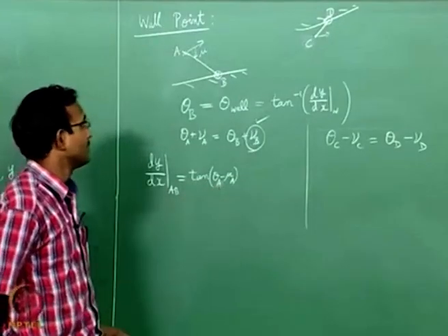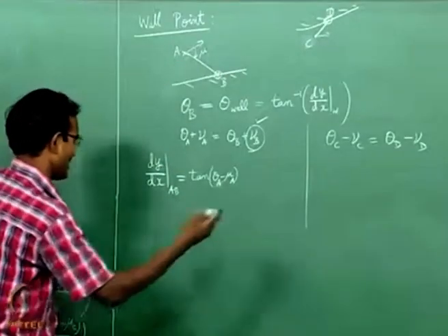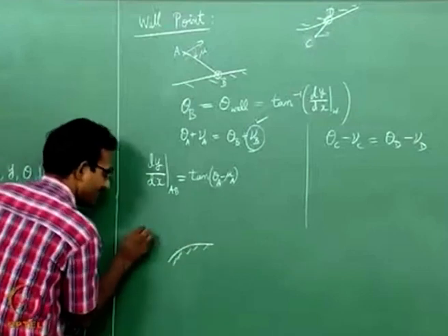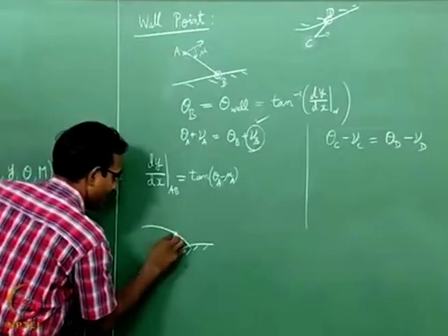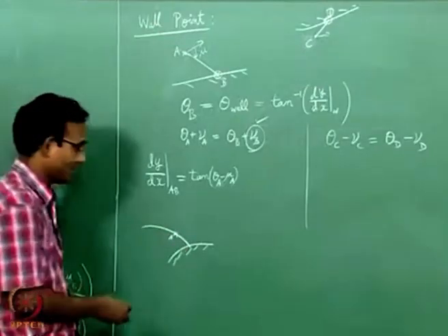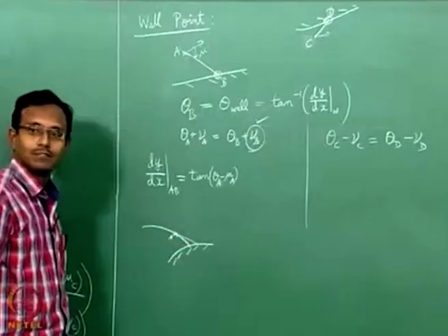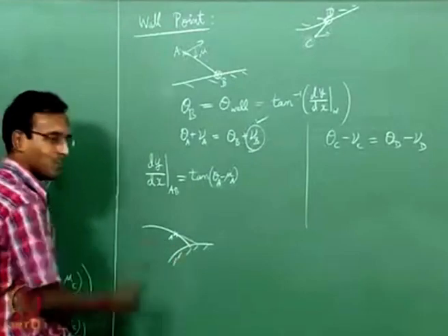If I do this, if the wall is curved a lot, I will have a lot of problems. I will give you an example case. My wall is curved like this, and my characteristic is curved like this, and currently my point A is here. If I have such a situation, if I just use the slope from here, I am going to meet this point, which is actually having some other slope here. So, this will have more errors.